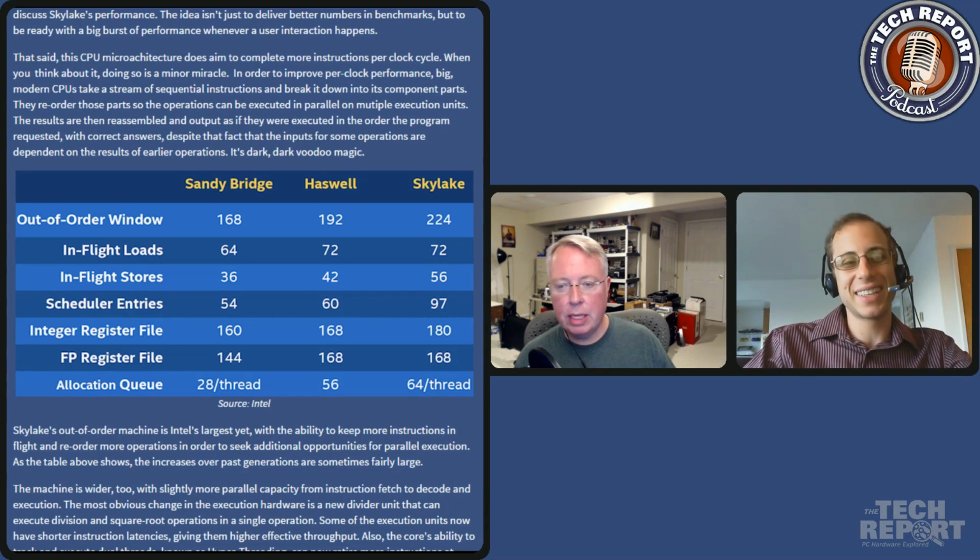So when you say that they're clock gating, you're talking about clock gating registers? I didn't get into a detailed discussion, but it sounds like they can detect certain phases of execution when you're more memory bound. And then, yeah, you could imagine clock gating the scheduler, parts of the integer register file, parts of the floating point register file. There are so many different ways to do this.